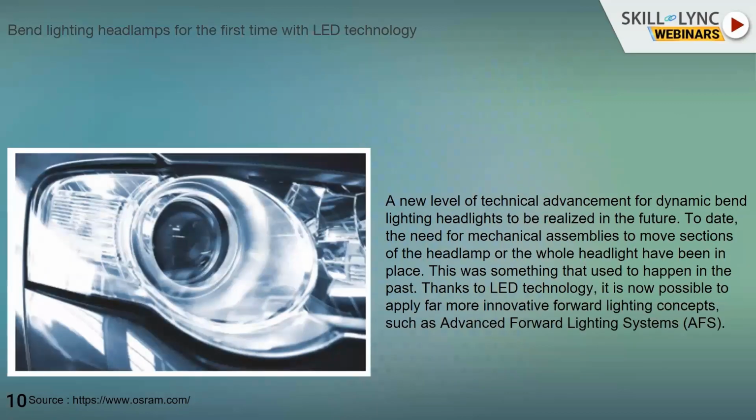Coming to the bending technology, in part one also we have covered this. This is a very unique feature, an adaptive system of the light, called the advanced forward lighting system. It turns automatically when the road is bending, and you do not have to do anything. It will also reduce the focus once a pedestrian is in front of the lamp, so they will not get the glare of the light. And if any vehicle is coming from the front side, it will reduce the light on that vehicle and give sufficient light to the driver.